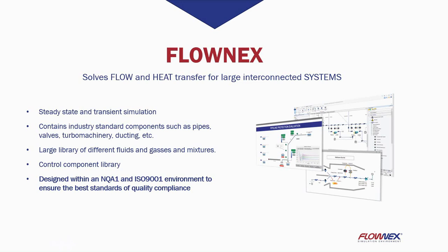So what is Flownex? Well, Flownex solves the flow and heat transfer in subsystems and large interconnected systems, which includes steady-state and transient simulations. Flownex further contains industry-standard components such as pipes, ducting, and turbomachinery, which can be easily interlinked in the easy-to-use user interface.